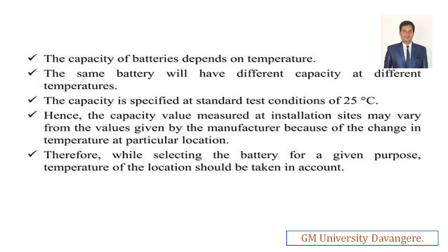If we carry the battery to different regions, we'll have different temperatures. Based on that, the charging and discharging will also make a lot of impact on the batteries, right? Because if you take the batteries to other regions like Shimla, where the temperature is very low, the degradation will also make a lot of impact on the battery health. So that's why you have to focus more on the temperature conditions.